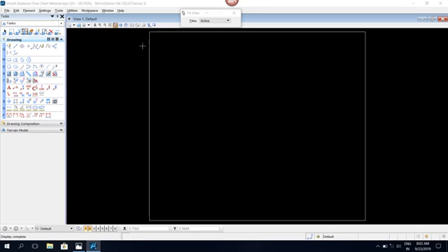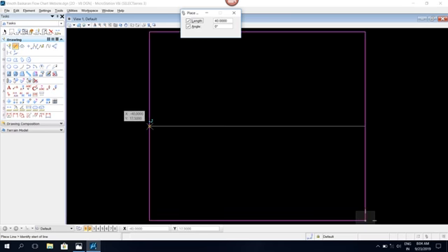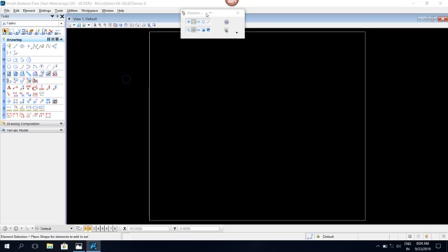Fine. Then we have to create a line, two-dimensional, 10 units offset from the top edge of the rectangle. So I'm going to place line. We know the length is 40, then the angle is 0 degrees. If you press enter, you can click wherever you want. I am just placing the line at the top edge.